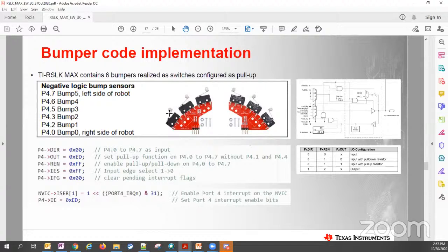So how can we make use of it for our bumper mechanism? If I program some of the pins to become inputs, usually they begin to float because input pins are of high impedance, not stable, because I want to sense something.